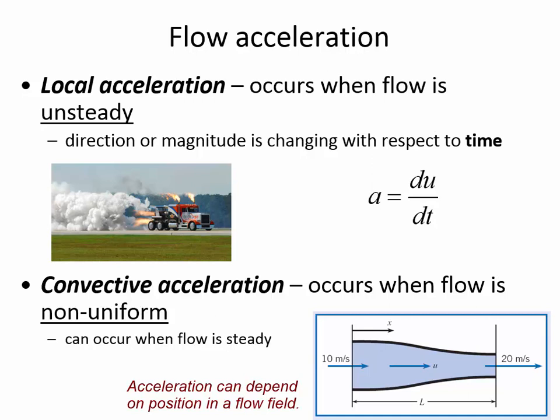That's one of the differences between liquids and gases, is that gases are easily compressible. And when we talked about the compressibility of liquids, we found out that it requires enormous, really, really high pressures even to compress a liquid by less than 1%. And so for all purposes, we could say that liquids are basically incompressible. So the reason I bring it up is, as water goes through a nozzle like this, it's not going to become more compact. Just because we have the diameter decreasing doesn't mean the water is going to squeeze into the smaller space and exit at the same velocity.